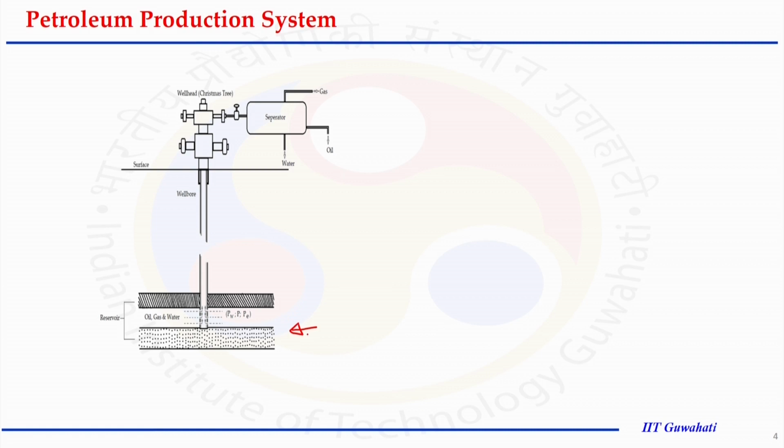Under the radial flow, the fluid or the gas is flowed from this porous media by the pressure gradient, and the pressure at the sand face is PWF. We also call it the bottom hole pressure, and that is PWF. The flow is happening from PE to PWF. That also depends on several factors we discussed in detail in the IPR relation.